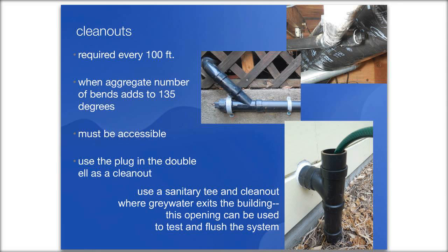And the cleanout has to be accessible. It's not going to do any good if it's somewhere where nobody can reach it, or it's right up against the wall. You're supposed to have 2 feet in front of it that you can reach it from. And like we said, in the double L's outside, we like to put that little plug that kind of acts informally as a cleanout.